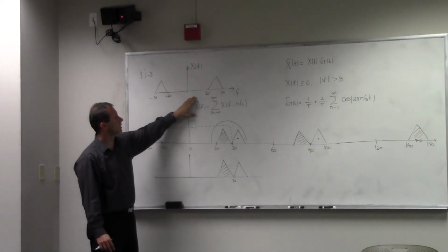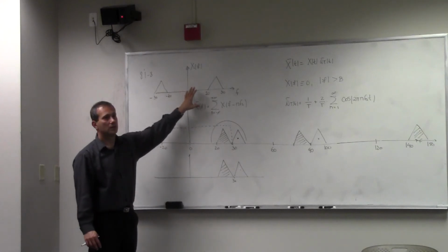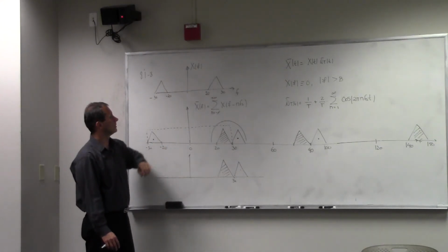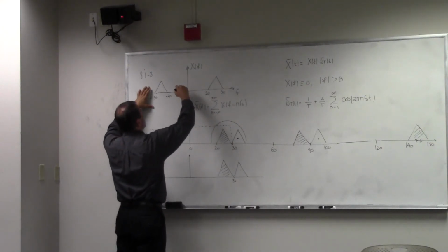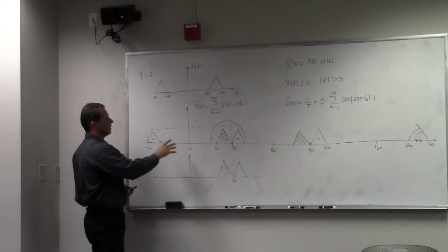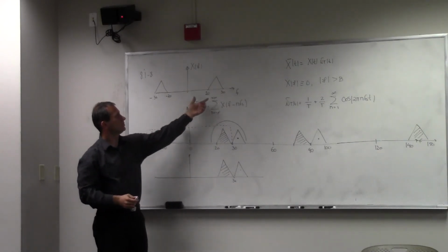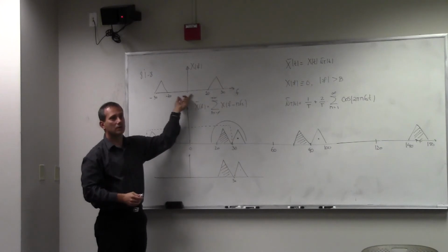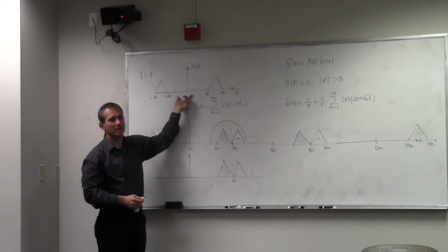Let's sample this at a lower frequency, so I can translate this into something different. But when the signal is band limited, then you what? Let's do this. Let's shift this over to the baseband, and then sample that at 20 kilohertz, right?